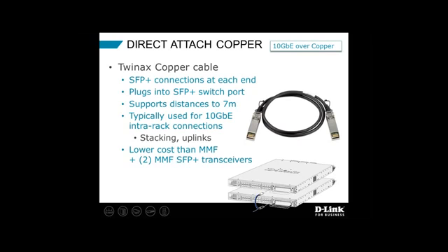I don't want to discount another 10 gig over copper technology called direct attach. A lot of people call these cables direct attach copper or DAC cables. This is basically a twin-ax copper cable, and if you look at that cable, there are connectors at each end that are SFP+ style connectors.